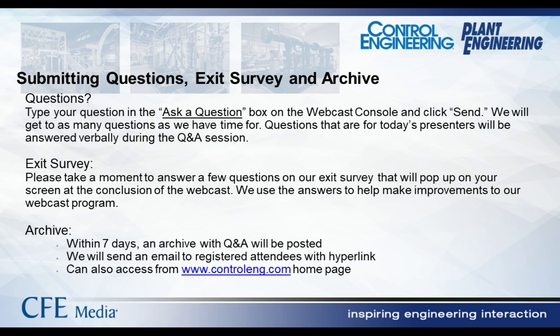And then maybe a follow-up question to that would be, a risk assessment isn't a static thing, right? Those need to happen over time, especially if any changes occur. Yeah, identifying the risks and then mitigating them up front before the cell is turned over to operations is a requirement. And then definitely if something changes, if new parts are introduced or some kind of maintenance task is identified that wasn't identified previously, the risk assessment should be updated to reflect those changes and the appropriate mitigation.